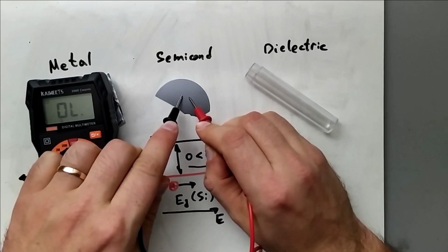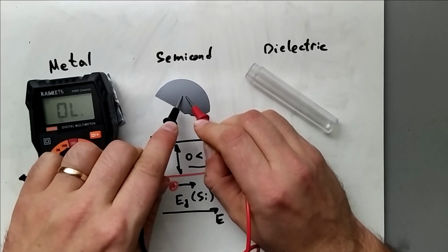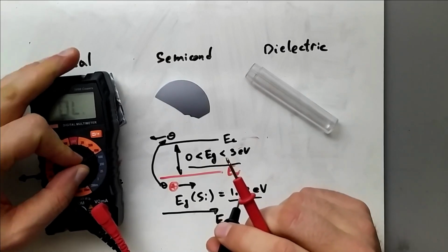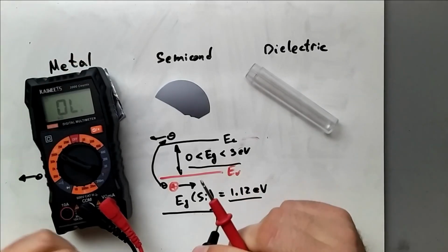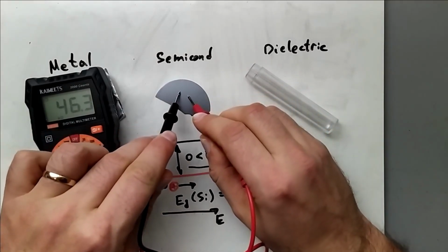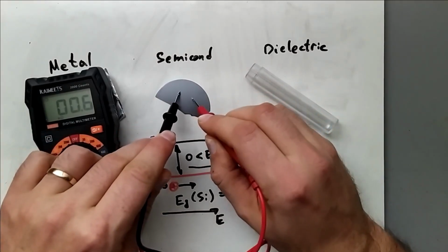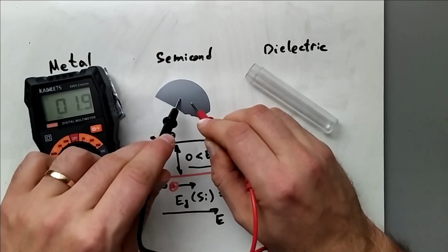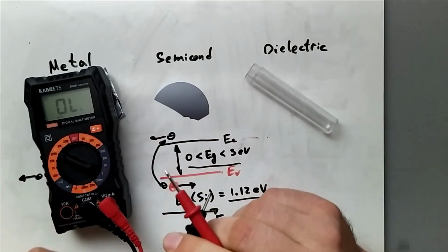No signal is shown on the multimeter, and that is actually because the range is at 200 ohms. So if we switch it, let's say to 200 kilo ohms, let's try again. Oh, you see there is some current flowing through the sample, so we can measure.